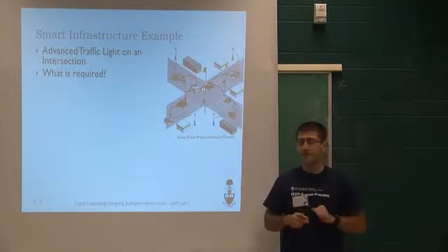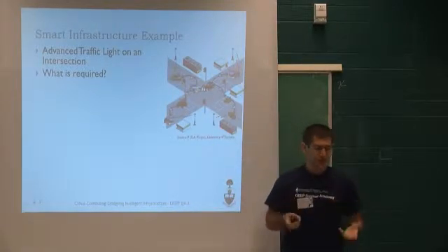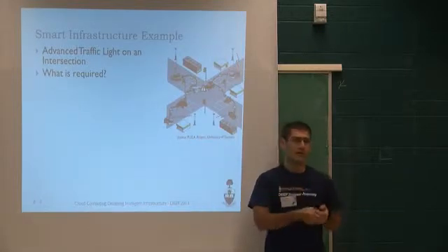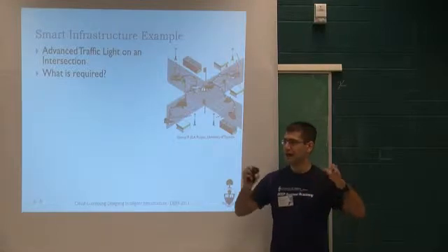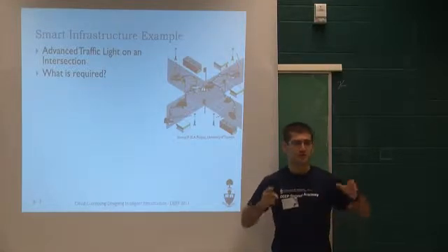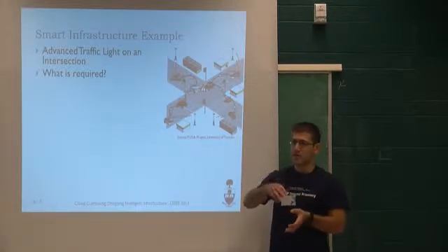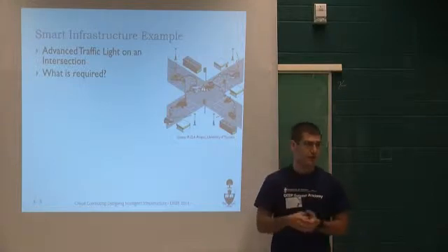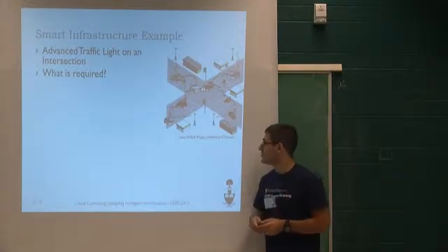You use that in order to create pre-timed cycles. So if you don't have pedestrian lights, if you don't have additional things that you're detecting, you'll have set times. So let's say 40 seconds for this cycle, then the opposite, let's say the east-west one, would be 25 seconds if the north-south one has a higher volume, right? Because you want to optimize based on that.